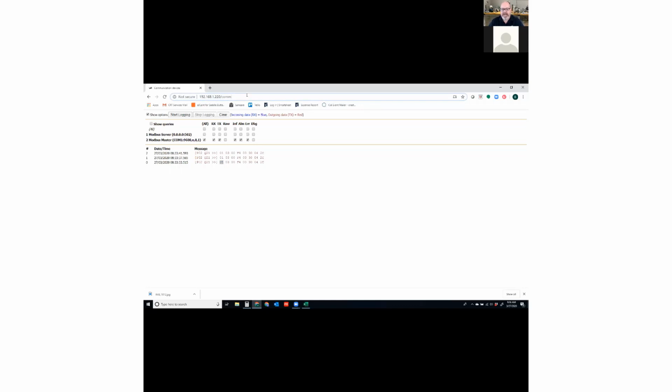It's all just communication. With the FlowX flow computer that we use, a lot of times the information that we get is what we call tag based. We do these little web queries, and when we ask for information, we're asking it from our web services. In this case, what I just did, a very intensive request, was to ask the flow computer to give me back every single tag inside of it.